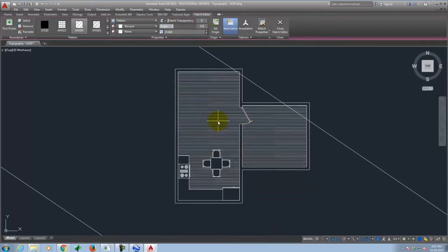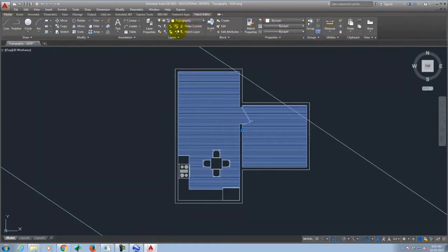One of the things I recommend with this is that it ends up being a much lighter color, so that you don't overpower your drawing. If I were to select the hatch, for example, and click on the home ribbon, I can come back and adjust the line weights. The line weights are available here under the Properties menu. By default, it says by layer, by layer, by layer. Each layer that you have is associated with a particular line weight and line type, and color, for that matter. But you can manually adjust the objects.